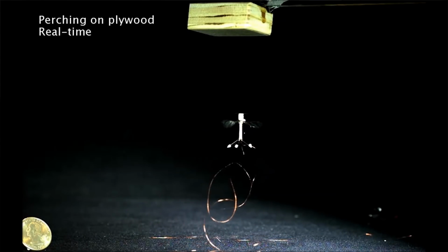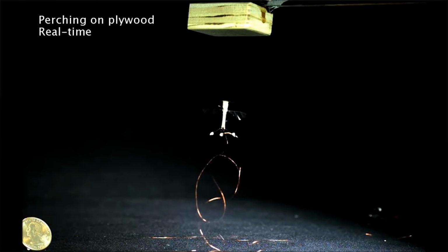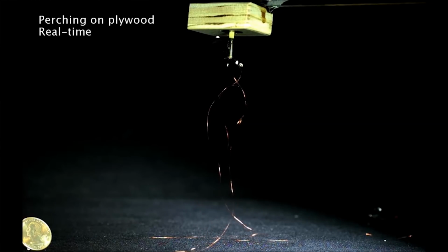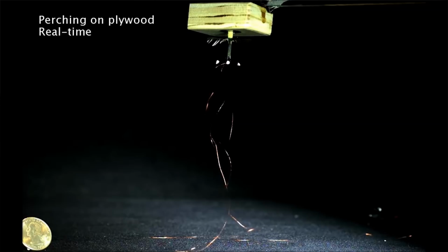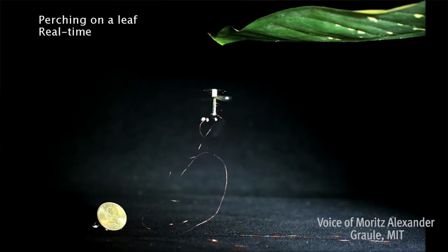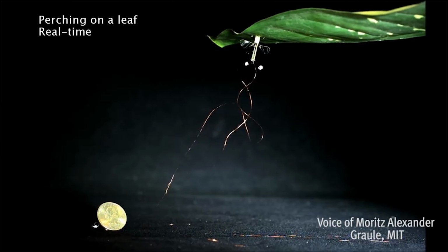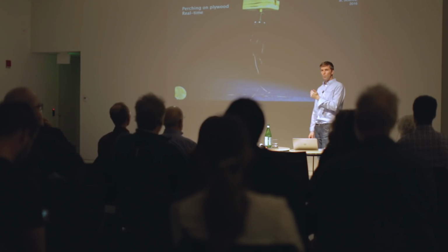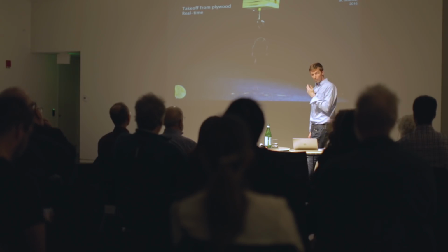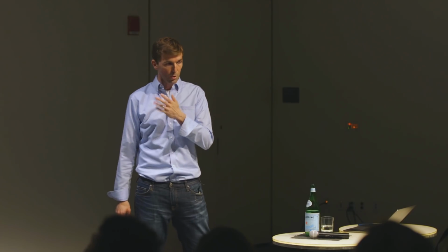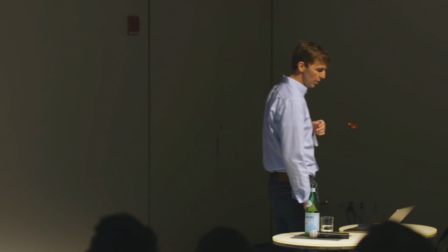A little bit more recently, we've taken advantage of the relatively high payload that we have for these systems and developed some perching strategies that leverage active electroadhesive that we put on the top of the device and allows us to perch on whatever we want. The motivation here is simple: the energetics of flight at this scale are so power hungry, so energetically expensive, that you're not going to fly around for too long without expending your battery or whatever power source you have. So perching strategies make a lot of sense for any real mission.